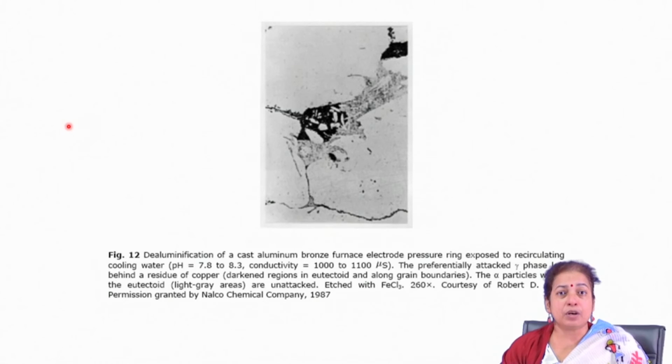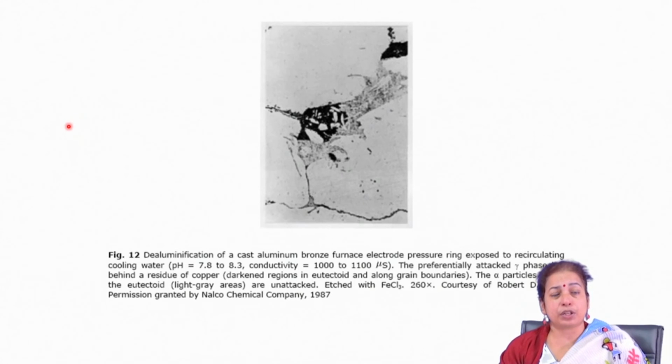You have to homogenize the alloy prior to its application, or you can also get rid of this particular problem by typical cathodic protection, anodic protection, and also by painting operation. These are the things applied in general corrosion to combat the general corrosion problem. Similar solutions can be applied, but it is better that you take care of the overall microstructure carefully, so that there are no grain boundary second phases present prior to its application in the environment.